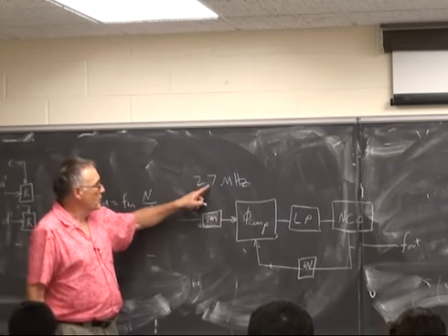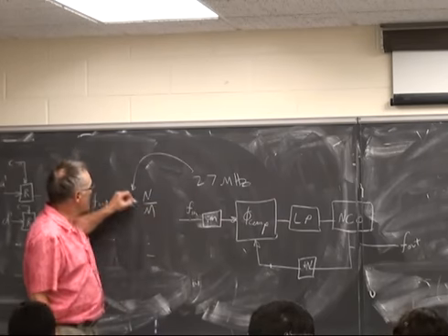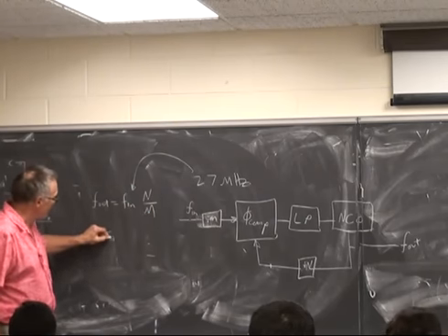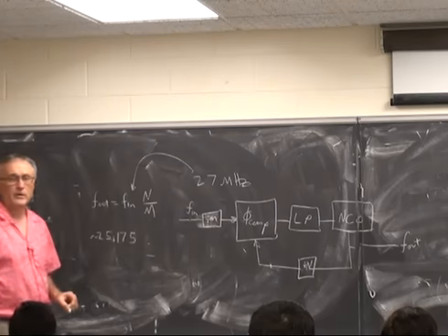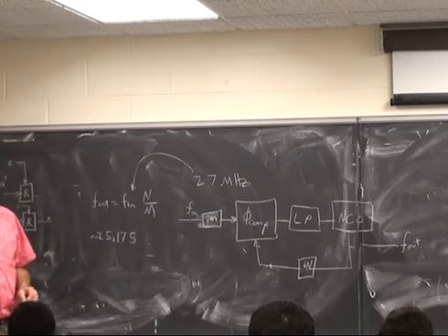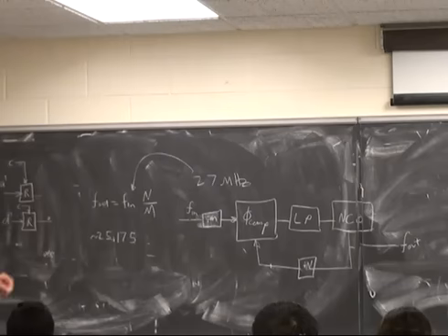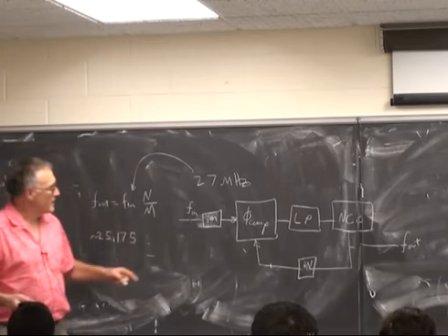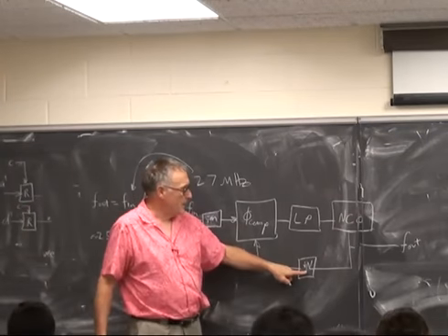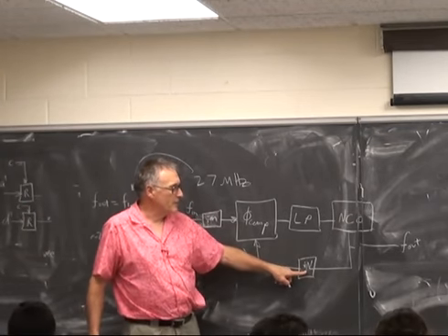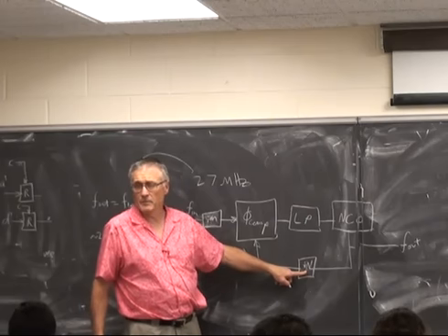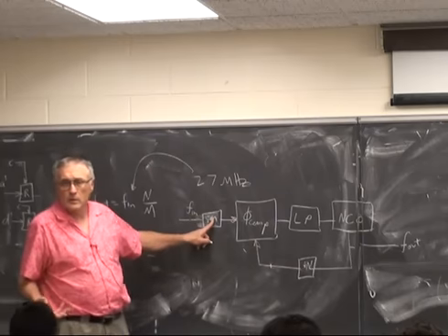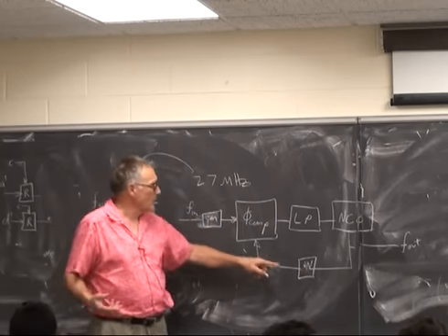So 27 megahertz is F in. If we pick N and M correctly, we can get approximately 25.175 megahertz output, which is the VGA clock frequency. Now, I'm not sure how many bits the on-chip phase lock loops have, I just can't remember. I looked it up, but I can't remember. But I think it's on the order of 5 and 4, or 6 and 4.